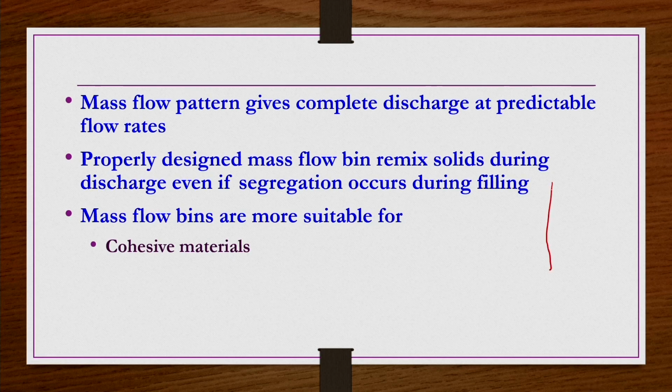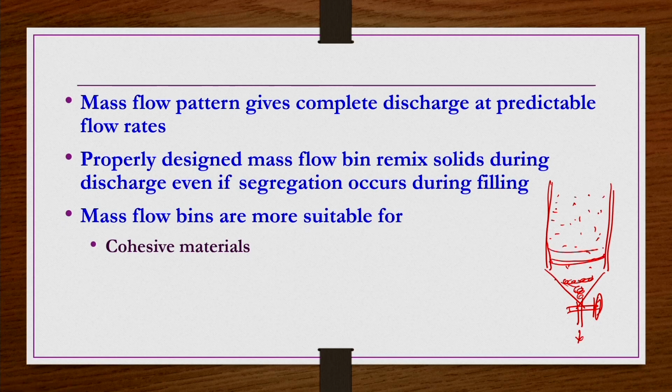Otherwise, what happens in general? Let us say we have a bin like this, right. Even if you have a bottom opening, something like this at the bottom, and your material is a cohesive material, sometimes when you open the gate or operate the feeder to take the material outside, whatever material is in this region may be drawn out. But beyond this, they may form a kind of bridge, something like this.